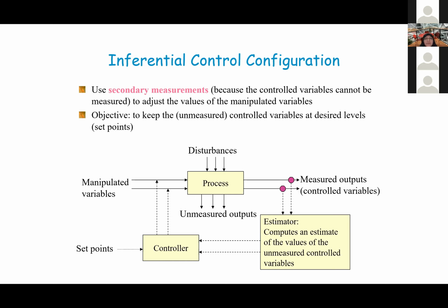And if you remember from your analytical chemistry class, a gas chromatograph will take some time for the sample to go in through the capillary tube before it's being separated, before we know what is the composition. So an online GC is very expensive and usually it will cause a lot of time delay. So in the end, some people just take samples and then do it several times in a day.